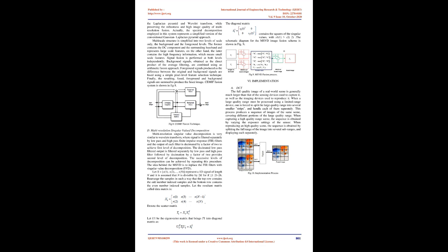The study of wavelets, and even the term wavelet, did not come until much later. As a special case of the Daubechies wavelet, the Haar wavelet is also known as dB1. The Haar wavelet is also the simplest possible wavelet. The technical disadvantage of the Haar wavelet is that it is not continuous, and therefore not differentiable. This property can, however, be an advantage for the analysis of signals with sudden transitions, such as monitoring of tool failure in machines. The Haar wavelet's mother wavelet function can be described as follows.